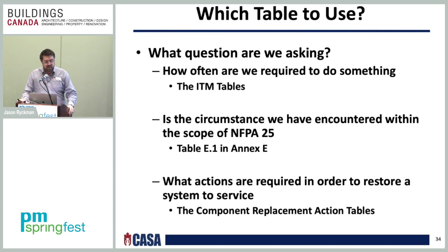Are the circumstances we have encountered within the scope of NFPA 25? Are we actually talking about NFPA 25 or another standard? You look in Table E1 in Annex E for that information. And then what actions are required in order to restore a system back into service, which we just looked at, is the component replacement action table that you would look at.